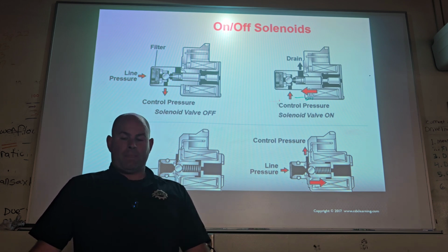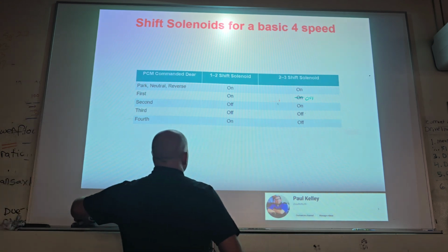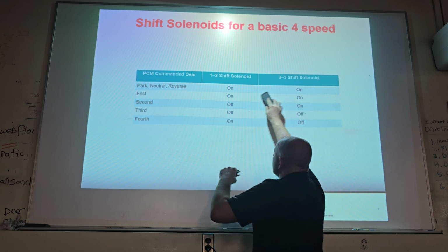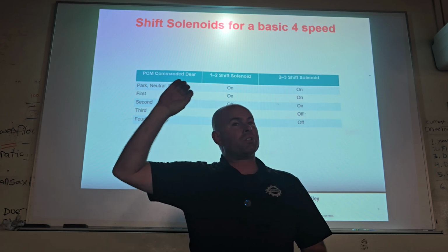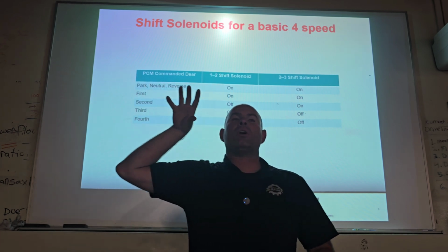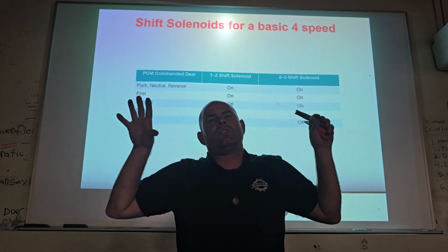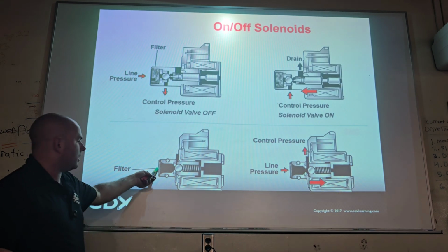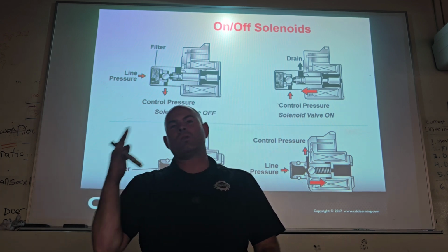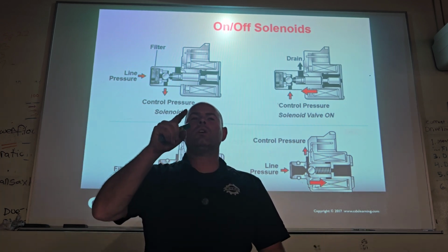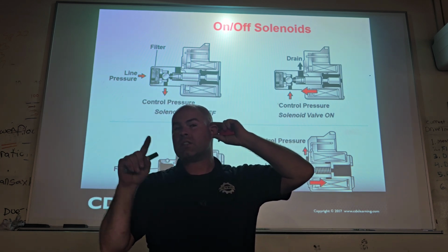Okay, ideally, if I could say ideally, I would go over here, and do you remember this shift solenoid over here was the 2-3? And this one was the 1-2? And if you go way back, remember Toyota said SL1 and then it had pressure sensor SL1? You see now, if you had the pressure sensor for shift solenoid linear 1, you could use that sensor to diagnose that the fluid was actually making it there. So if you applied that solenoid, you could look at pressure sensor SL1 and verify that that fluid is making it to the circuit, and therefore you know that that filter is not clogged up and that that solenoid is not only electrically working but mechanically working as well.